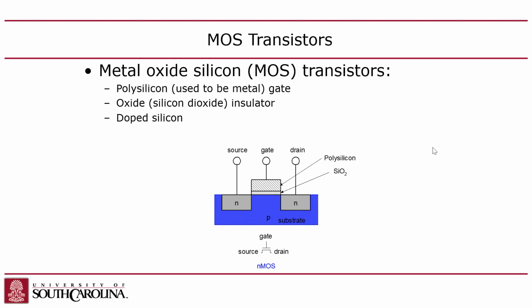So with the transistor, you have a substrate, which is usually p-type. You put the diffusion areas in it, which are little islands. And this is fundamentally how chips are made, is you start out with a substrate, which you grow, and you inject it with these little diffusion areas. These are the active areas, right? So these diffusion areas are basically made by starting out with p-type. The substrate starts out as all p-type. And then you start doping it with n-type, right?